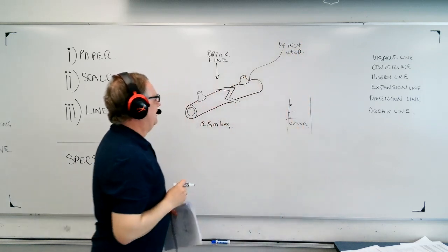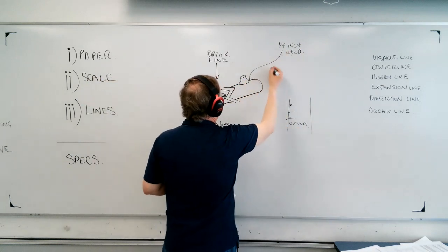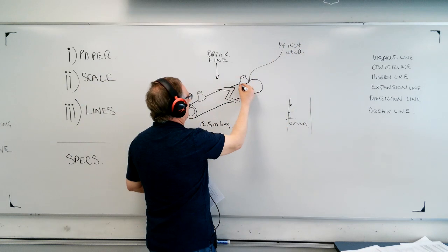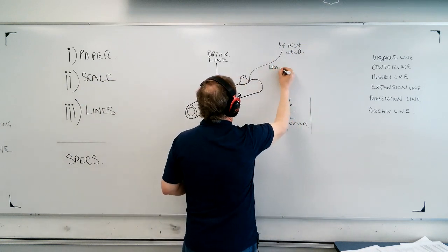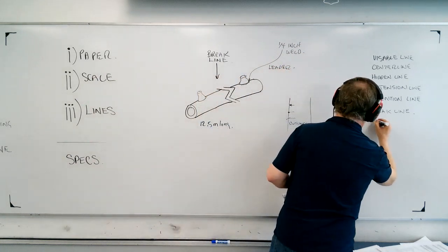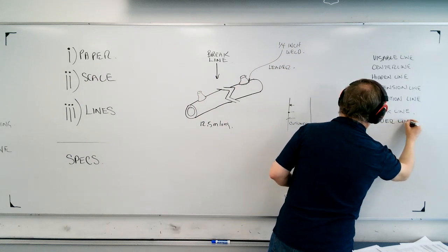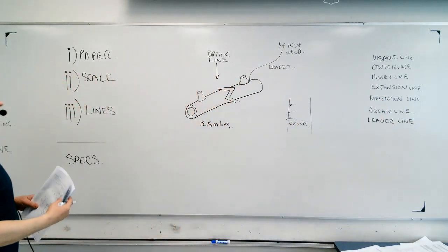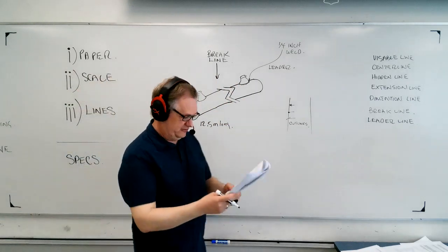Okay, so if I said there's got to be a 1/4-inch weld around that fitting, and look at that line that I put, I put it so you know that weld's got to go right here, all the way around that, right? And so this is called a leader line, and it leads you from the note to the specific location. Leader line. Okay, so these are the mechanics. This is just understanding, and it helps you. If you don't know what the lines mean, then it's a lot tougher when you start looking at it.